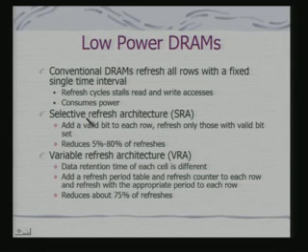One is what is called selective refresh architecture. Add a valid bit to each row and refresh only those with the valid bit set. What does that valid bit mean? Valid bit means that the row really has data. Otherwise it may have don't care. If it is a don't care, then there is no point refreshing those rows.